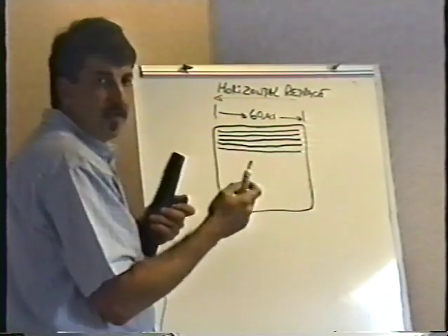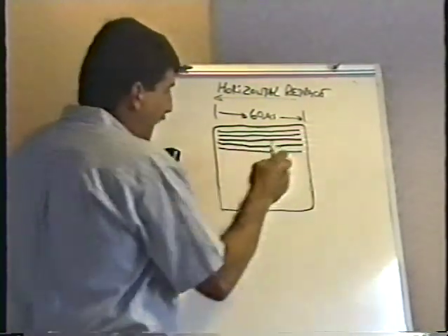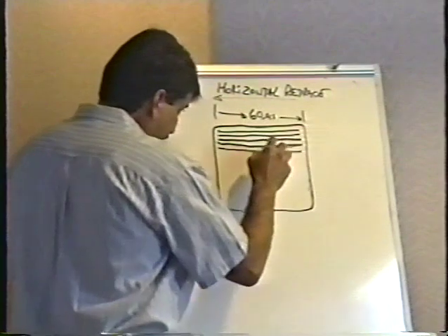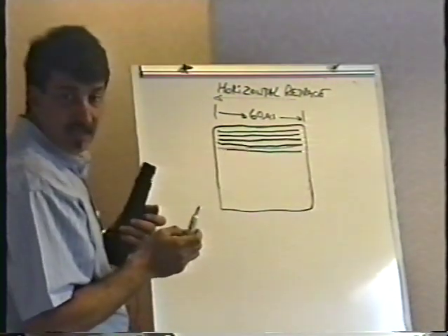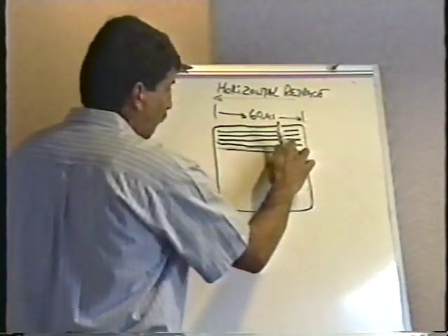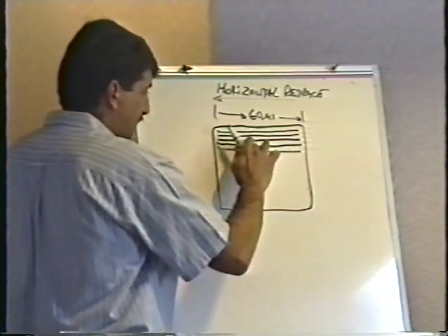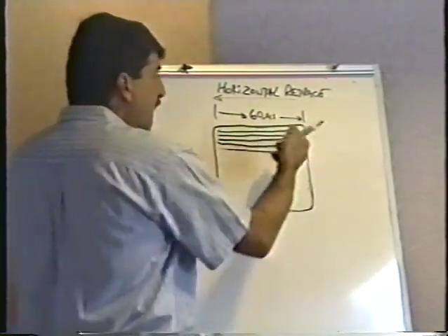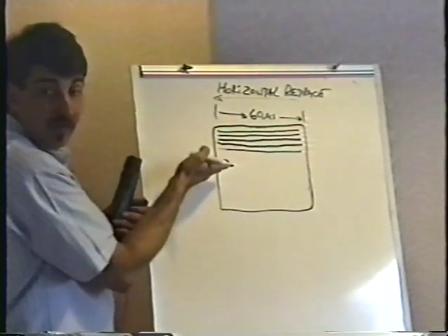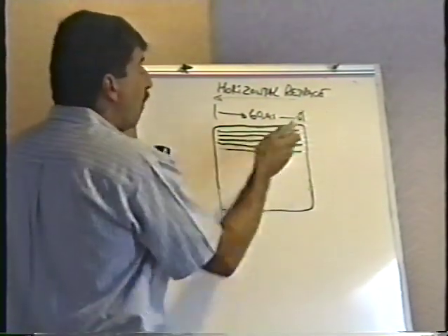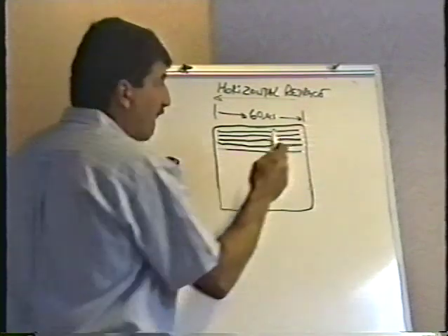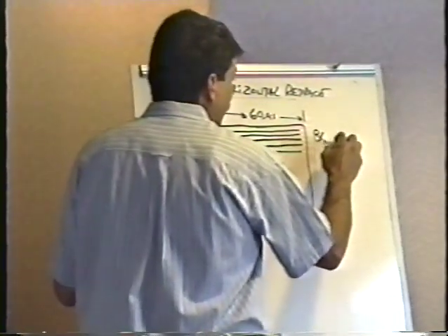Well, naturally, we don't want to draw any line on the way back. If we did, we'd see a line in between the lines like that. These lines, by the way, are called raster lines, and I'll explain in just a second why they're called that. But we don't want a line in between the lines on the way back. So the beams are all turned off on the way back, and there's a separate circuit that does this.